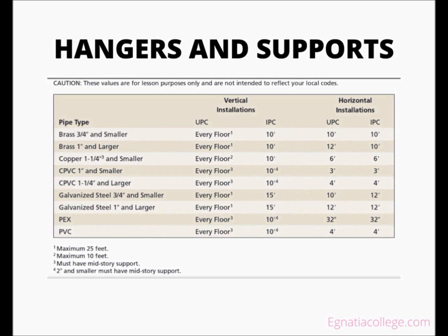Water piping stub-outs require a support bracket or other adequate means of support to eliminate the possibility of damage to the piping when wallboard or cabinets are installed. Earthquake-prone regions are regulated by seismic codes and may require special methods and spacing allowances to support piping systems. A plumber must be knowledgeable about these specialized codes.